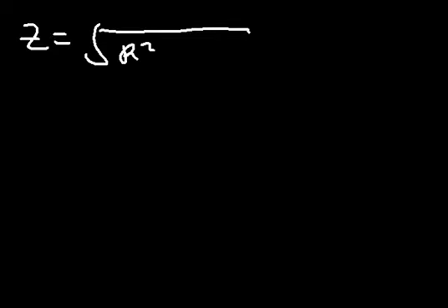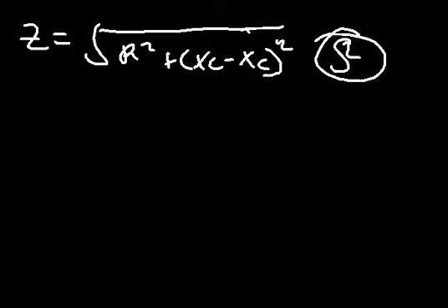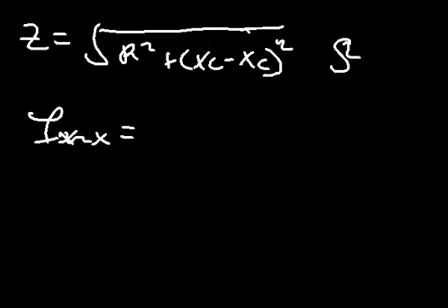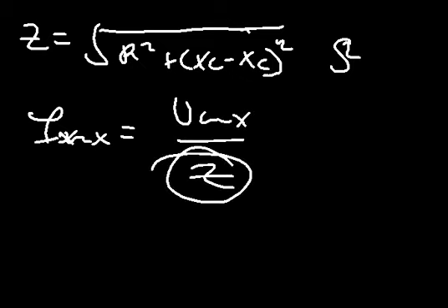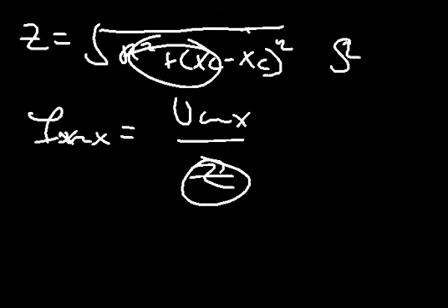And what is our impedance? The impedance is symbolized as Z, which is equal to the square root of R squared plus (XL minus XC) squared. So this is the formula for the impedance, and it is given in ohms because it is part of the resistance. From that perspective, Imax will be given as Vmax divided by the impedance from the previous formula we have recently talked about. So in this case, the impedance is the same as that.